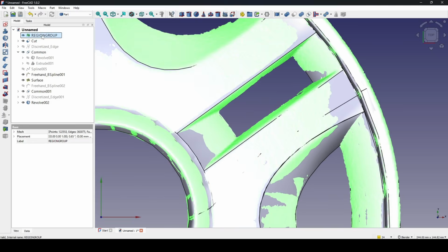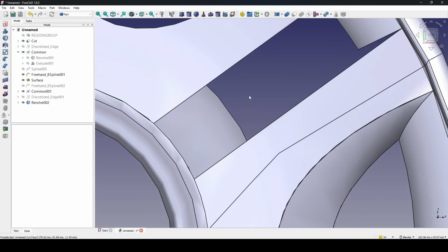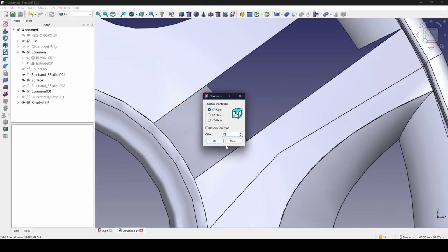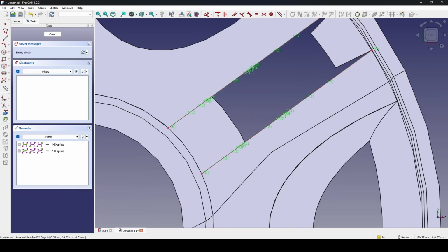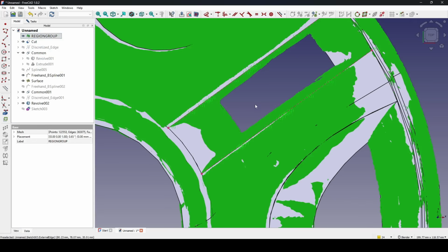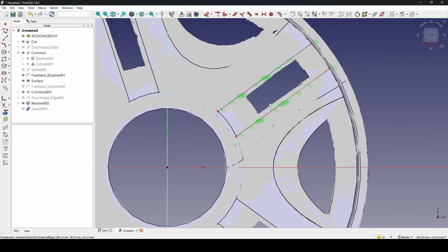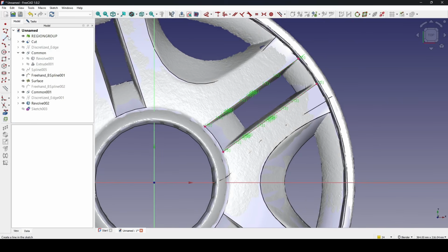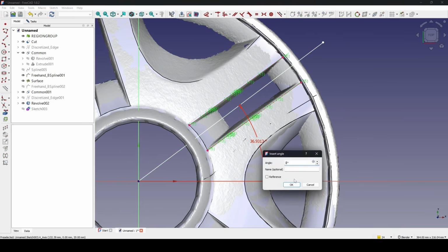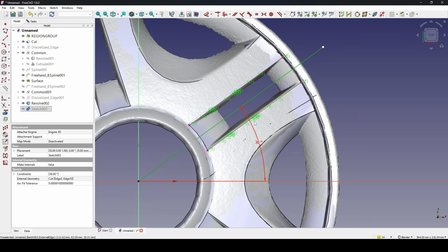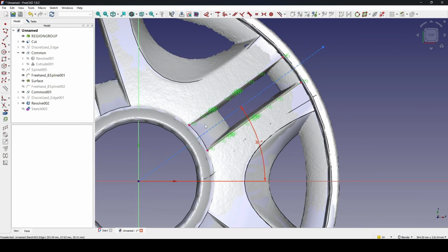And I show the mesh. Sorry, I should create a new sketch in the top and move this one up to 20. And I will reference these 2 lines. And I show the mesh. From there, I can do the same. I can create a line in the middle, set the angle to 36, and change this one to construction.